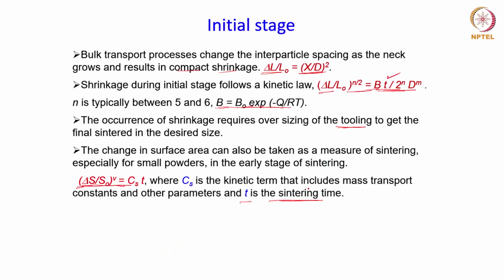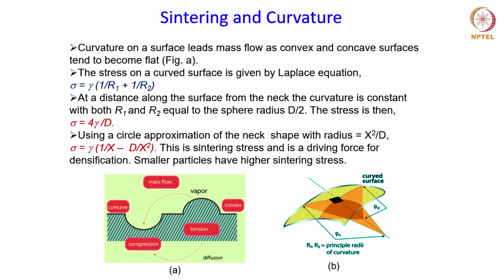Okay, so before we finish this class, let's take a moment to summarize it. So to summarize, we can say that the curvature on a surface leads to mass flow as the convex and concave surfaces tend to become flat. So that tendency for the surfaces to become flat is a driving force for the mass flow.